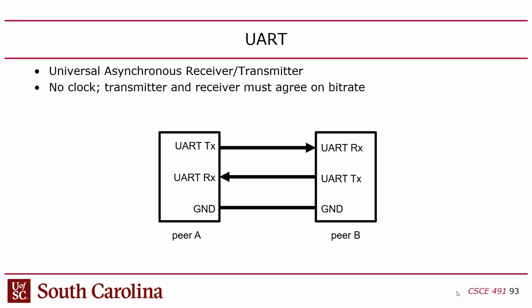But that's not good enough, because eventually you're going to get an error no matter what. Even if you run UART slow, you're still going to get an error, right? And so for that reason, they have also provided the ability to detect errors called parity. This is the reason why we're going to talk about parity here, where we didn't with SPI. SPI didn't need parity because of the timing that it does, the edge timing. Whereas this guy needs parity because inevitably you're going to get errors on UART. It is not a question of if but when, because there's no phase management of the clocks.